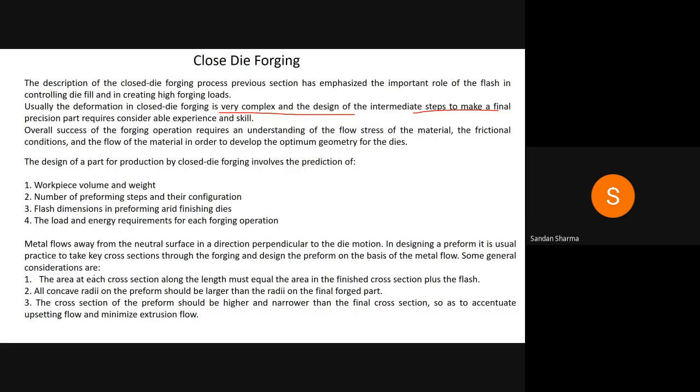If you try to reduce the machining part, it is better to go for preforming condition using the powder metallurgy route before going to forging. So you'll have a preformed condition that you'll be pressing again in your die punch setup, so the cutting part, machining part will get reduced.